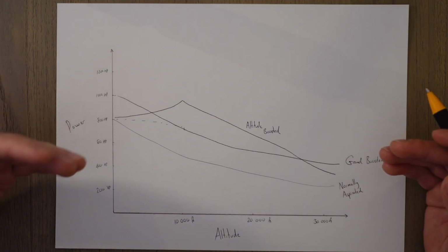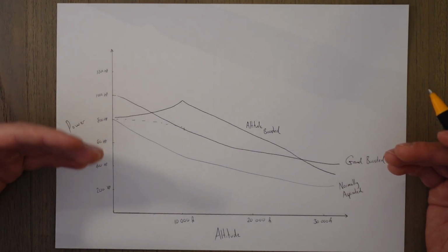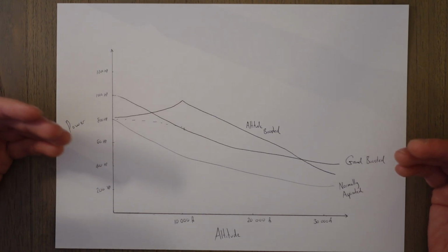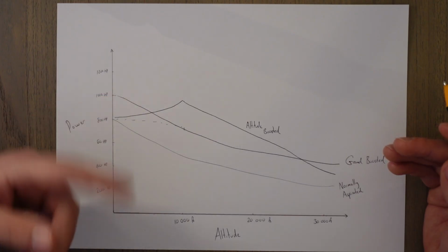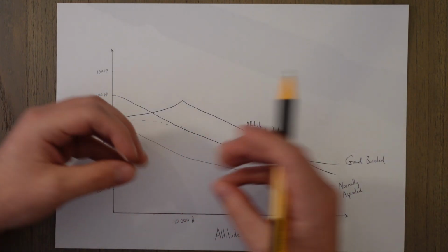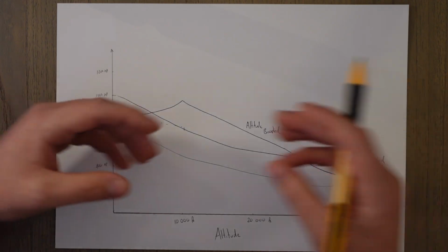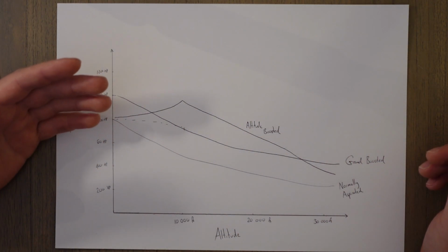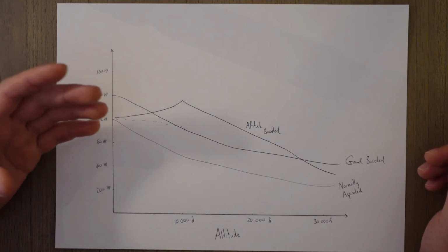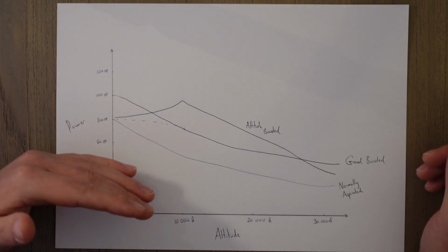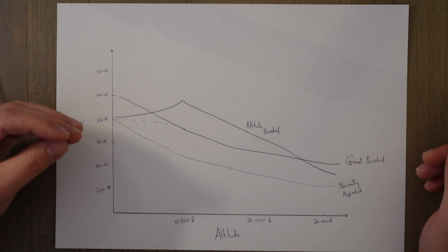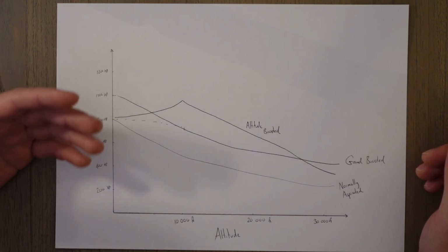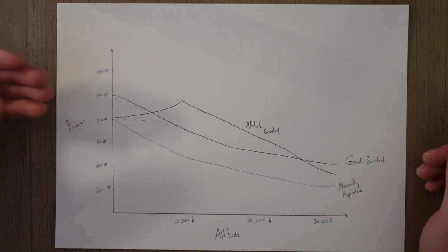It essentially uses gears from the engine and the gearbox in order to turn something called an impeller. An impeller is a device that squeezes a gas by rotating it very quickly and forcing the gas out of the center because of centrifugal force. And as it reaches the edges, it enters something called a diffuser. And the diffuser slows the gas down slightly, trading dynamic pressure for static pressure. And when the static pressure suddenly increases, so too does the volume and temperature. And this is the gas that is then sent to the engine.